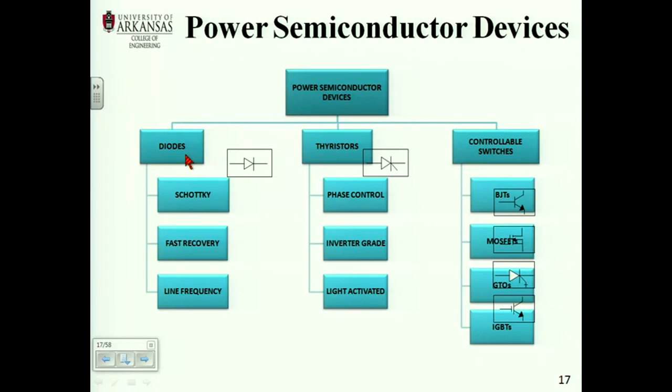And very soon you are going to start seeing a silicon carbide diode connected in anti-parallel connection with a silicon MOSFET, 1200 volts or 1700 volt devices. As the modules become available, designers are going to start using it. And here is the Schottky diode, right?